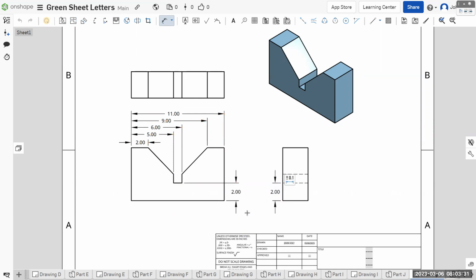And I'm going to say just the fact that we can go to a contour is giving the viewer much more information, like what this 2-inch dimension actually means. Looks better in that position. So we'll keep it there. And that means we're following the same set of logic for the other one. And then the only other height is total height, which could go front view or right view.